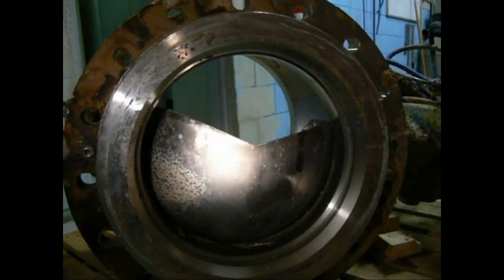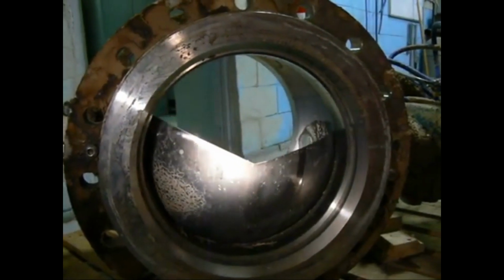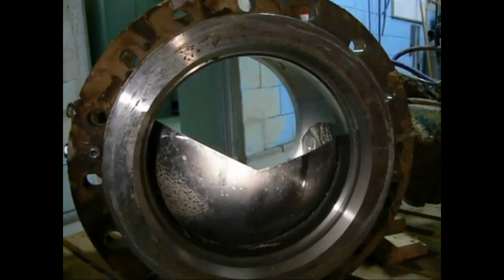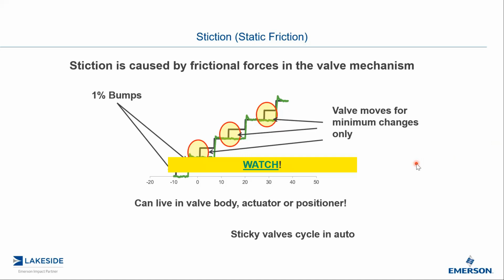There you go. You see all these jerky motions, and what that was doing was the valves were actually hunting, therefore causing disturbances in the process itself. We actually ended up getting some money back from the valve manufacturer, believe it or not, because of the poor workmanship.